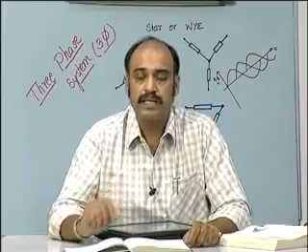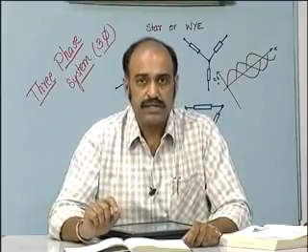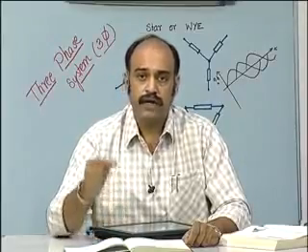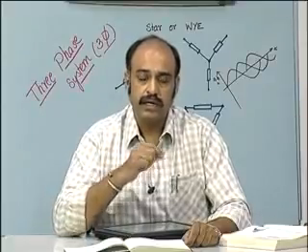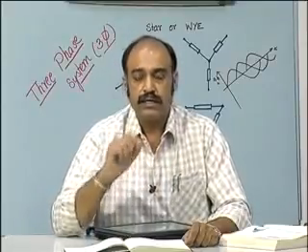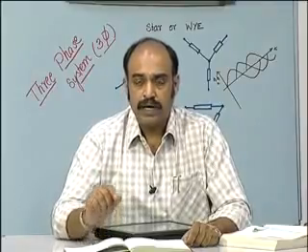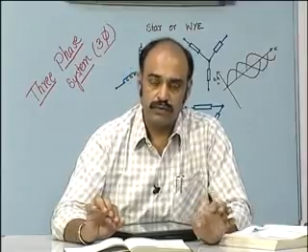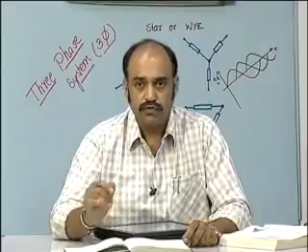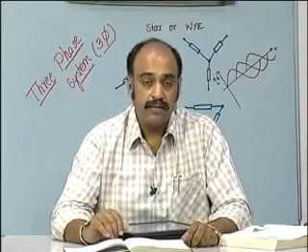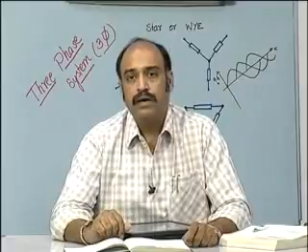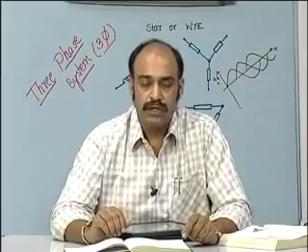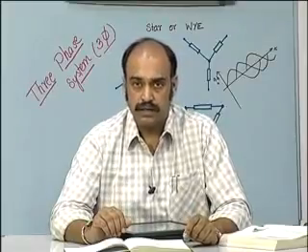However, if the load is unbalanced, then IA plus IB plus IC is not equal to 0, as we saw, and therefore we need to provide a return path from the load side to the source side, and that return path is through the neutral wire. Under such conditions the neutral point of the load and the neutral point of the source are connected, and it becomes a 3-phase 4-wire system. Under unbalanced conditions, if the neutral connection is not provided, then there will be distortions in the voltage wave shapes of the 3-phase loads.